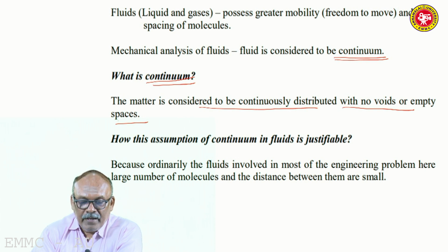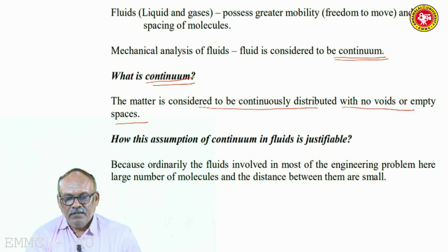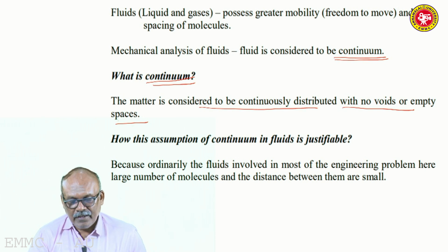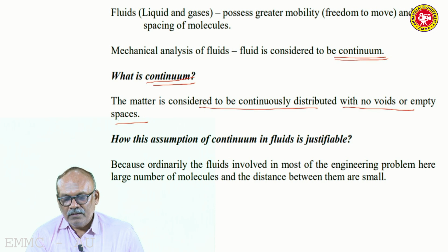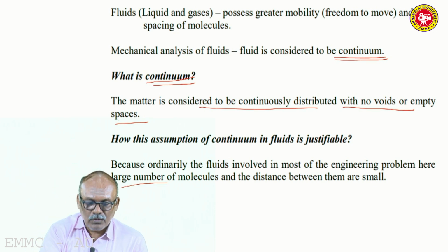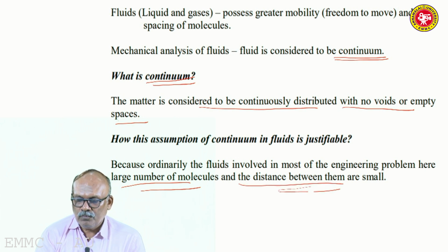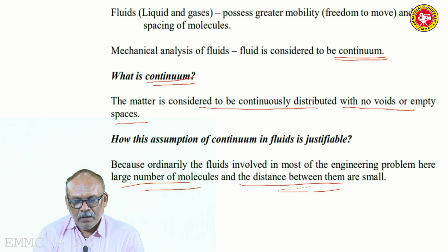But here we make an assumption that the matter is considered to be continuously distributed with no voids or empty spaces. So, how can we justify this assumption that the continuum of fluids is there? Because ordinarily the fluids involved in most engineering problems have a vast number of molecules, and therefore the distance between them is small. So this allows you the freedom to assume that the continuum in fluids is justifiable.